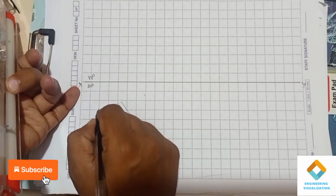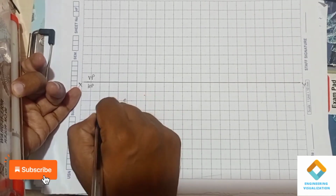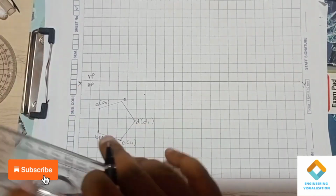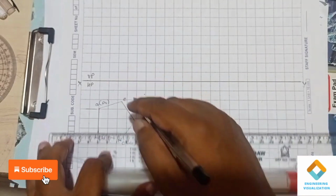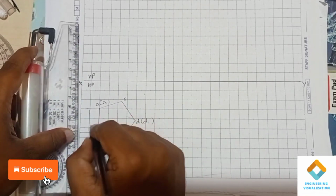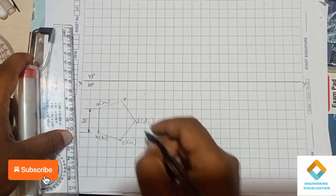You can give the naming for this. In a prism we know it has two faces, top face and bottom face. A, B, C, D, E is the naming of the top face. A1, B1, C1, D1 and E1 is the naming of the bottom face, which is not visible from the top view, that's why it is written within brackets. Now show the dimension for one edge here. I'm showing one edge as 25 mm. Mention 25 mm here.